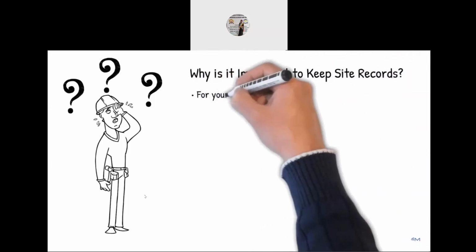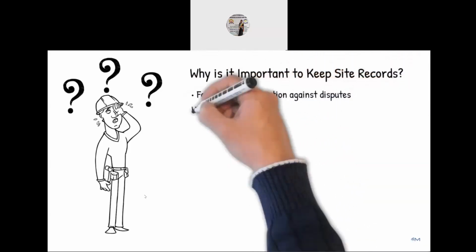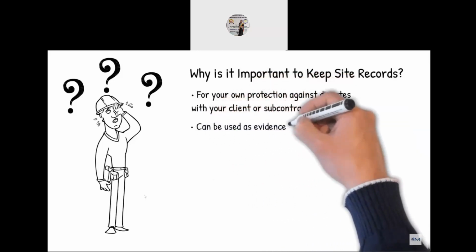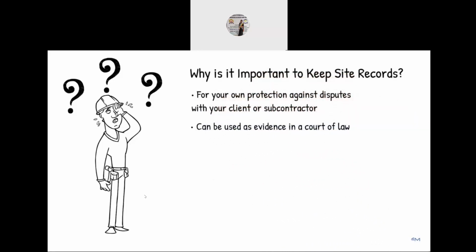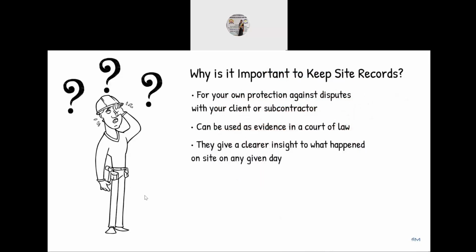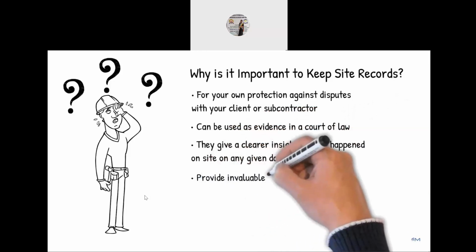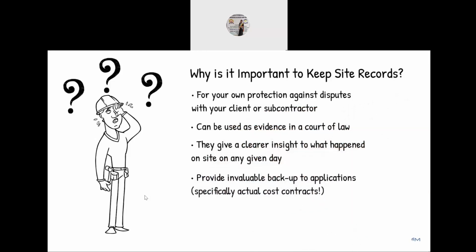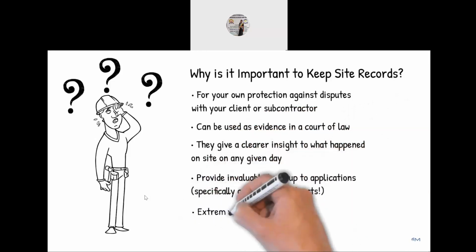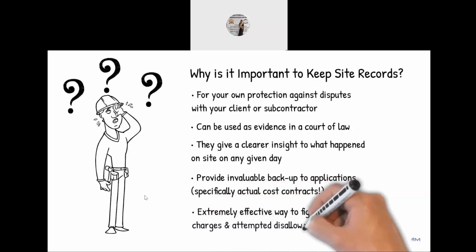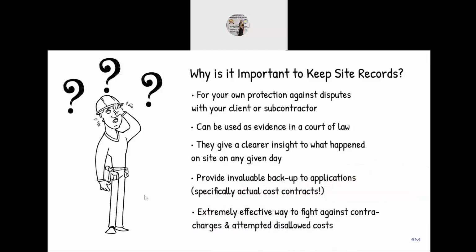They can be used for your own protection in disputes with your customer or subcontractors. Site records can be used as evidence of site activities in a court of law. Record keeping in construction projects helps you get a clearer insight into what happened on site. Perhaps most importantly, they are invaluable in providing backup to applications, particularly for actual cost contracts, and are one of the most effective ways to fight against an attempted contra-charge and to also combat potential disallowed costs by clients.